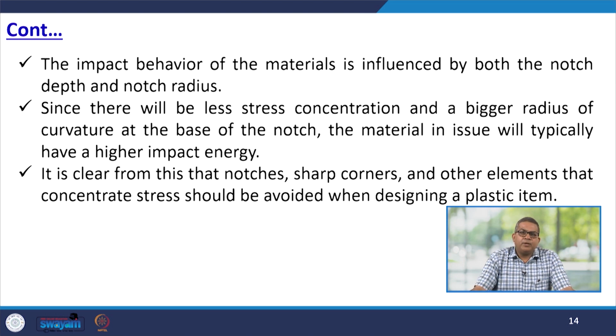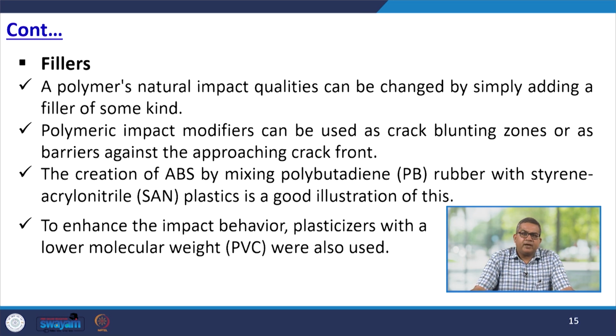The impact behavior of the material is influenced by both notch depth and notch radius. Since there will be less stress concentration and a bigger radius of curvature at the base of the notch, the material in issue will typically have a higher impact energy. Now, it is clear that notches, sharp corners and other elements that concentrate stress should be avoided when designing a plastic item. Let's talk about the failures.